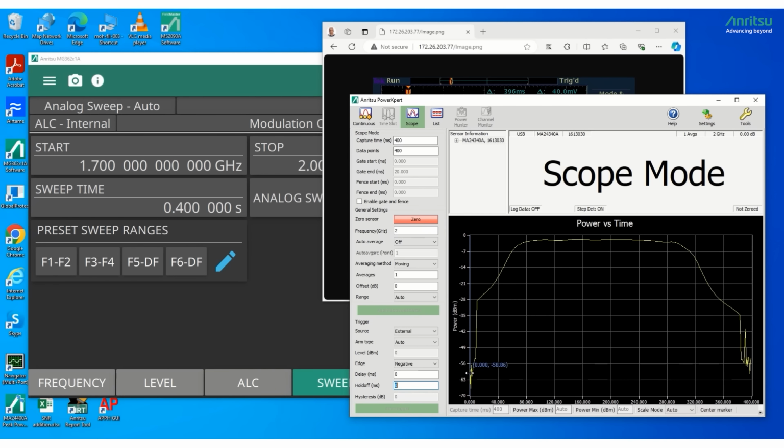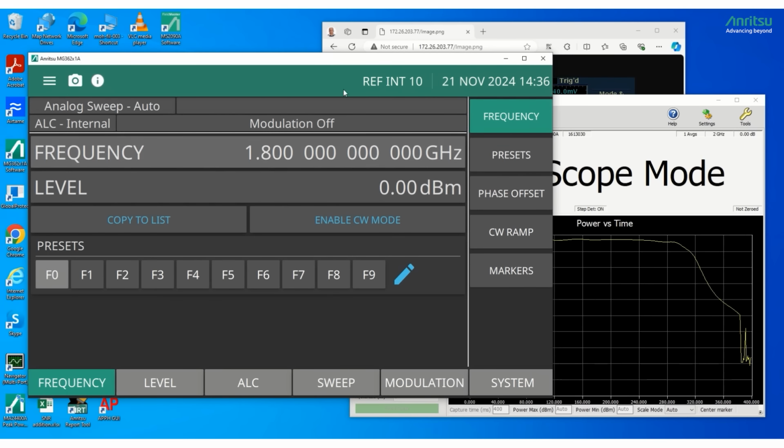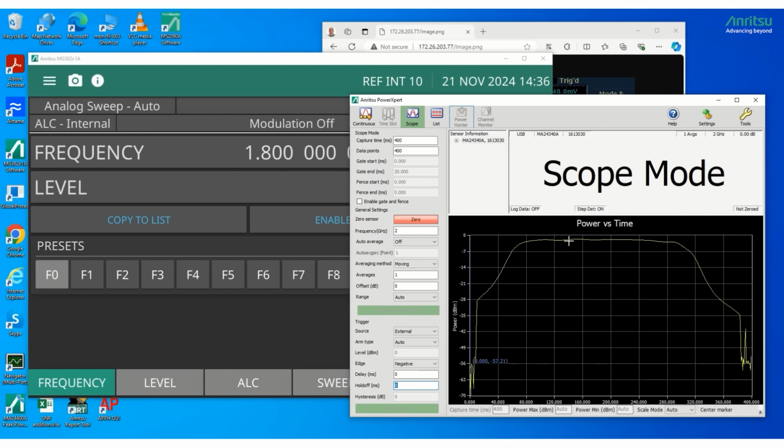And remember, we have set the output power to, let's go back to the Rubidium signal generator GUI, we have set the output power to 0 dBm, and with 0 dBm, you have some loss here, maybe 2 or 3 dB loss. And then the stop band is almost 50, maybe 55, 56 dB.